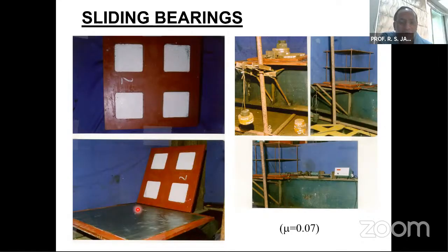However, there is furthermore an advanced sliding isolation system that has also been studied and developed. Professor Matsagar will be talking about the details of the advanced sliding isolation system, which has been developed and studied at IIT Delhi. On the right hand side, one can see an experiment to find out the friction coefficient between PTFE and the steel plates. So, a simple experiment that has been done.